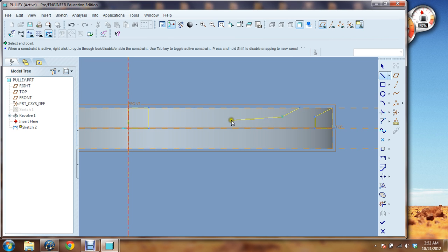And then I'm going to go all the way over here and make this line horizontal. And we're going to go ahead and lock it to the top of our plate. And don't forget, just as before, we have to close the sketch. I saw a lot of you guys doing this during the workshop, you weren't closing the sketch up. Well, I accidentally clicked the middle mouse button, so I have to close it, middle mouse, and now the whole